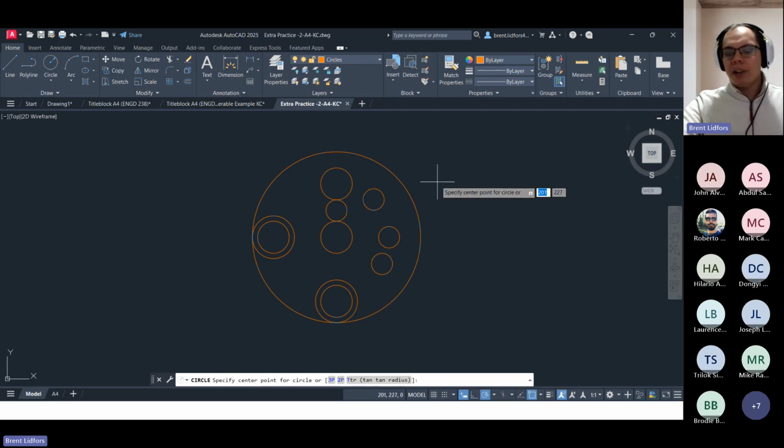So as a bit of a pointer, for both those of you that have handed it in and those of you that might still be working on it, since we talked about drawing with precision, I'm generally expecting you to use the precision tools that we talked about. So things like object snap tracking, object snaps themselves, polar tracking, polar snap if you choose to use it, that kind of idea.